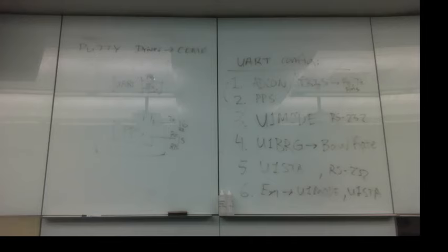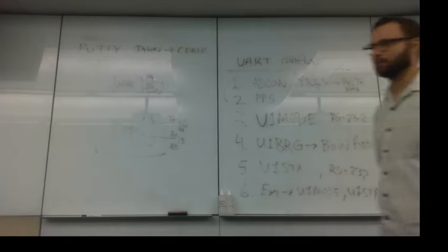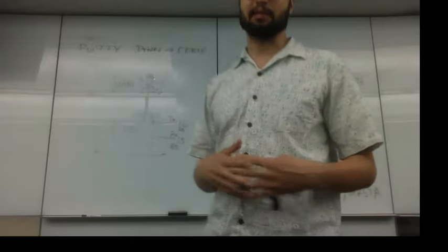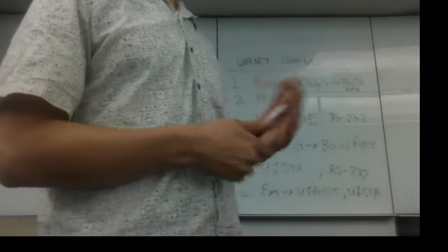And then you turn power on the PIC and you hope everything's okay. If it's not, then you close PuTTY, reopen it again, see if it works again. Then you uninstall the driver and reinstall it, see if it works again. Most of the time it works right off the bat, but with this kind of technology, there's always bus crashes and things that can go on.